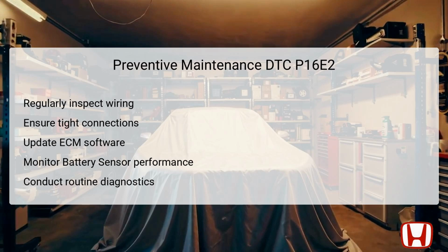Additionally, monitoring the performance of the battery sensor will help in early detection of possible issues, allowing for proactive measures. Lastly, carrying out routine diagnostics using the HDS can assist in the early identification of any potential new or recurring DTCs before they become more significant problems.